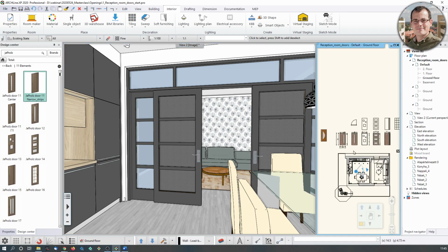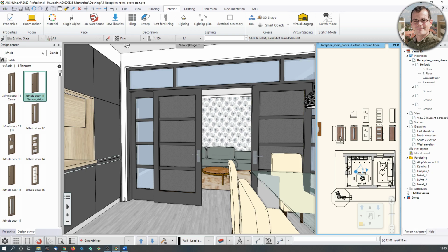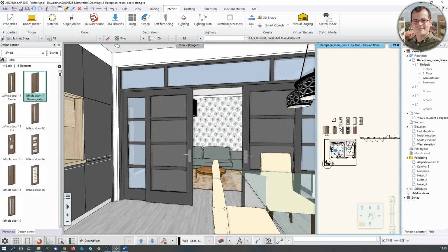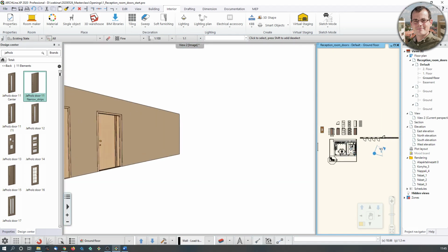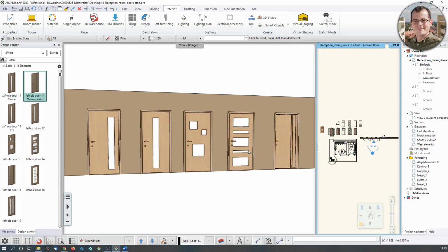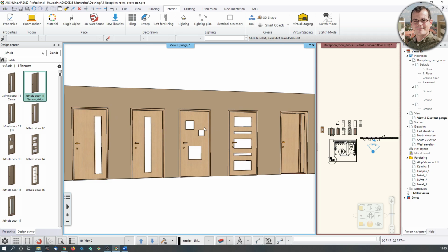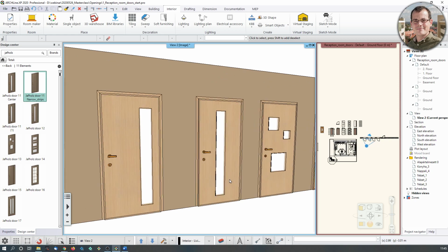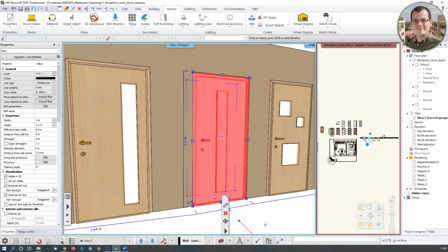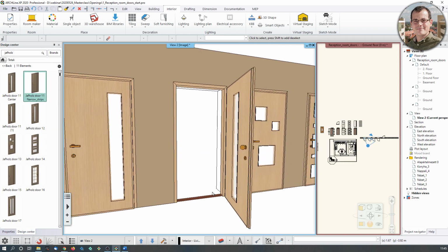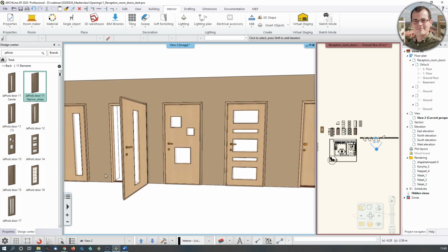And the last thing I showed you is the door wizard, where we created these wonderful inset doors. Again, you don't have to do this work because you can work with elements that others have created, but if you have the time, invest it into using the door wizard. That way you are going to create elements which look exactly the way you need them to be, and most importantly, you can open them up as well. So you can say that this is actually open. Wonderful. It's all parametric, it's all there. So there you have it.